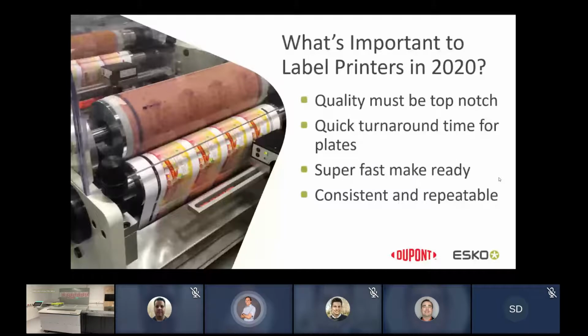And the XPS, man, that thing is by far the most consistent exposure unit you can get, with the LED diodes compared to the UV fluorescent bulbs. So much more consistent. When I go to customers to help problem solve print issues with their plates, so many times it ends up being that exposure unit, because those bulbs are old, because they've fallen below the threshold that we like them to be at, or they're just very inconsistent across the bed.